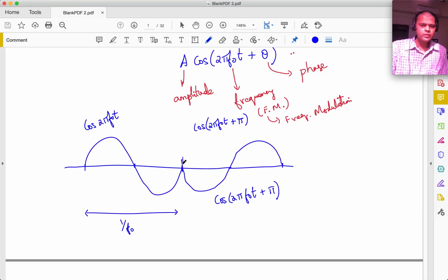So what I could do is, for example, send a bit, let's say a bit 0 here and a bit 1 over here in this way. This is one simple way to do it. So the signal is like this. Let's say the bit is 1 and bit is 0, I send this out. If the next bit is 1, I would send this signal out. And again, if the bit is 0, then I go back to this signal.